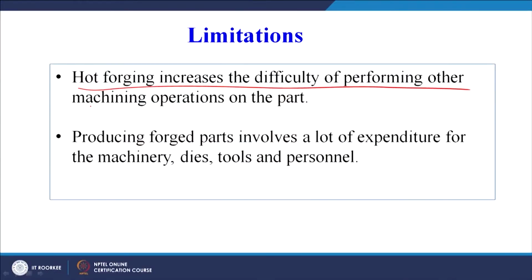So, hot forging increases the difficulty of performing other machining operations on the part. If we are doing the hot forging operation, later on if we need to do machining on the forged part, it may pose certain difficulties. That thing we must keep in mind when we are designing a product. We must not suggest that first we will forge this part to the desired shape and then we will machine it. So, on a forged part there will be certain difficulties for machining operation.